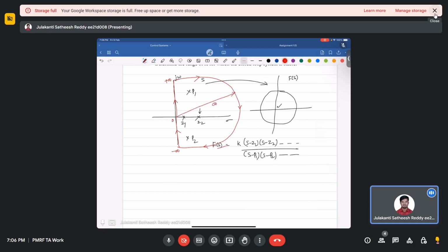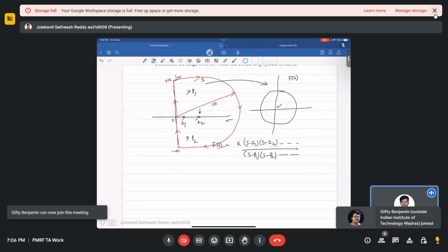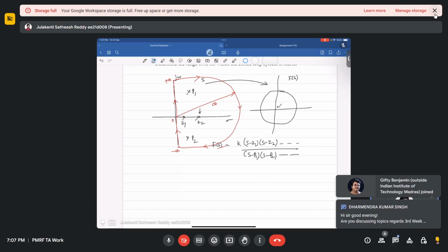Now for one pole, because it is in the denominator, and you are rotating clockwise, it gives minus 2 pi. Its angle is always measured with respect to negative to positive, right? So with respect to counterclockwise, agree? A clockwise rotation will give minus 360 degrees.